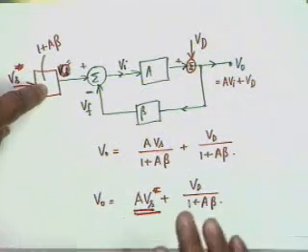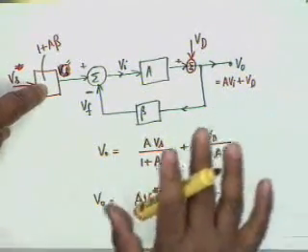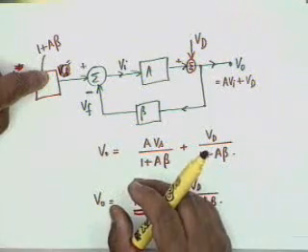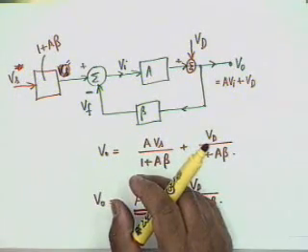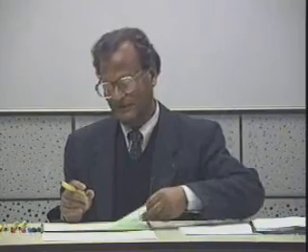Okay? And therefore compared to nonlinear distortion, the noise reduction is to a much lesser extent. In other words, you have to design specially a pre-amplifier with a gain of 11 or whatever the gain is, which is noiseless. You have to take special components which generate less noise, or have a special architecture for this circuit which is a noiseless architecture. So noise reduction is not as easy as nonlinear distortion reduction.